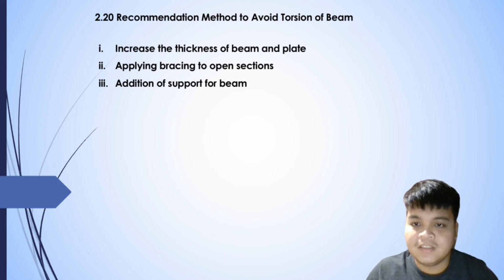Larger shear stress on a flat beam will occur at the center of the longer side. Stiffness increases with increasing beam thickness, and stiffness doubles with an increase in thickness of 0.1 mm. The effect of thickness on stiffness is far greater than that of blank holding force. The greater the arch height of the punch, the greater the stiffness.